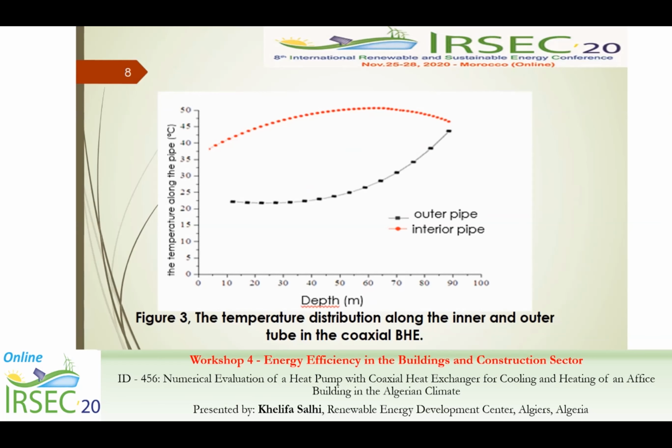1 year's simulation. The water in the production tube, after being heated in the ring, consequently loses heat to the water injected in the ring. The temperature of the produced water decreases from 35 to 31 during the simulation.